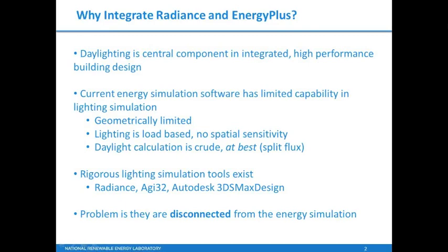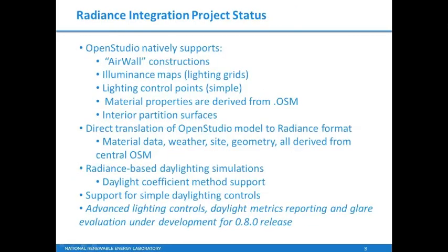The problem is all of those are disconnected from the energy simulation. It's a completely separate simulation tool. It's a completely separate model. It's probably a completely different modeler. So the problem with that becomes keeping the model synchronized. Keeping the assumptions about the glazing transmittance or the wall reflectance, for example, synchronized across the multiple models becomes a headache. So that's why we're trying to incorporate it right into OpenStudio.